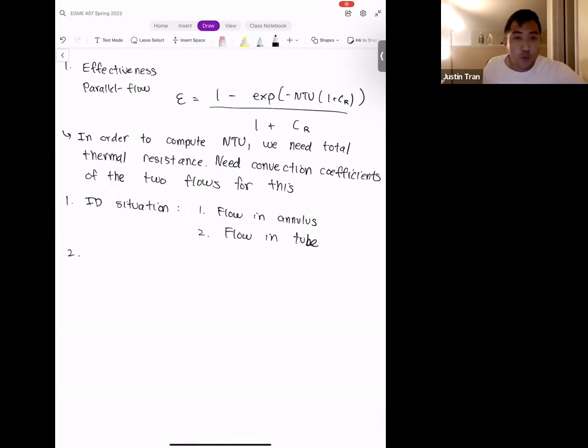And both our fluids here are going to be water. And so we're going to evaluate the fluid properties. Here we have a unique situation because both of our fluids are water, but they're at different temperatures. If you wanted to be more strict on this problem, you would compute two sets of water properties, one for the hot water and one for the cool water. For this particular problem, I was a little bit lazy, and so we're going to compute the water properties just at one temperature.